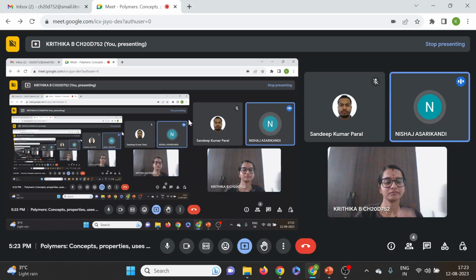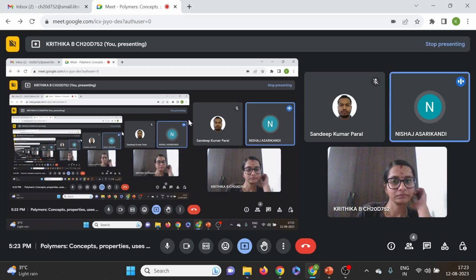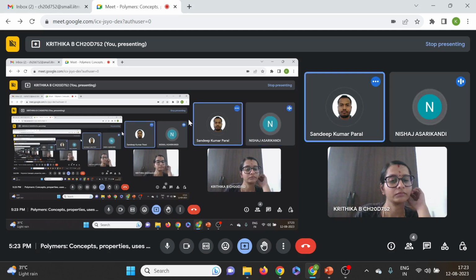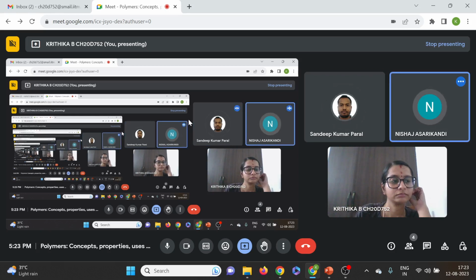Sandeep, I know what you are asking about. In TA, the crystallinity calculation is based on an internal parameter that is already set to 100% polyethylene. That is what it calculates. You cannot get a 100% crystalline material for all polymers. TA itself mentions this 100% polyethylene basis, so all the crystallinity they calculate is based on that value, even with other polymers.